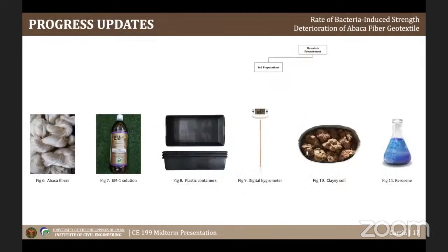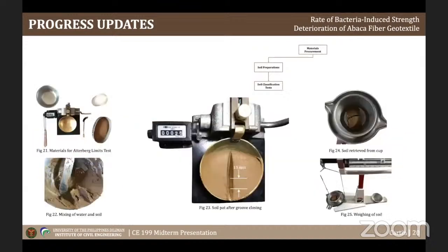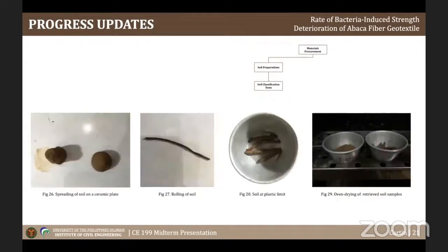The first step in the methodology, which includes the canvassing and procurement of the materials and test prices, was accomplished last January. For the soil preparations, I was able to conduct 3 trials of sieving, and also 3 trials of liquid and plastic limit tests. The following are the procedures and equipment used throughout the testing proper.